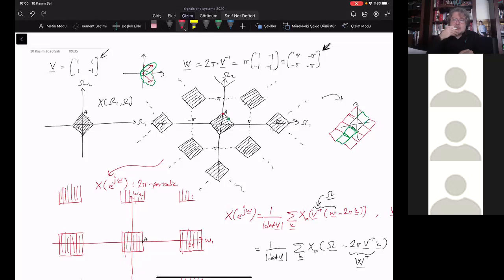An exam question that you will encounter will consist of this problem. I will give you a shape, a baseband shape. It's not going to be a diamond shape, but it's going to be something else. And with that shape, I want you to find the most efficient sampling. The most efficient sampling is the maximum sampling period, okay? The widest separation with which you still have no aliasing.